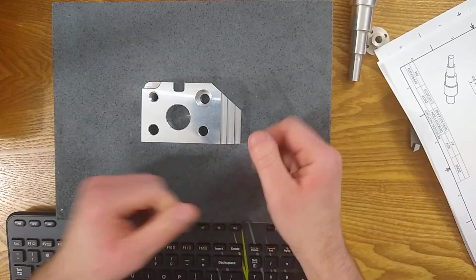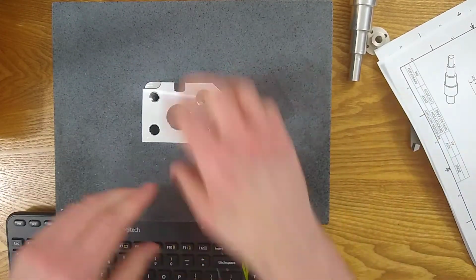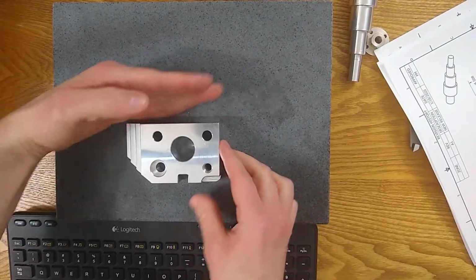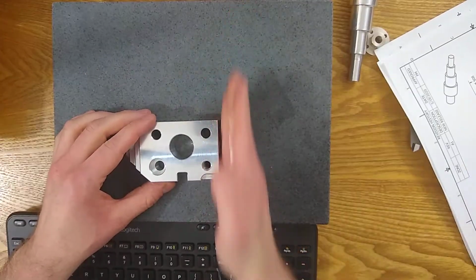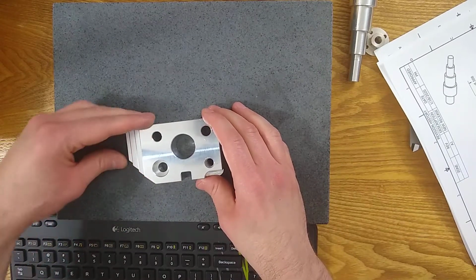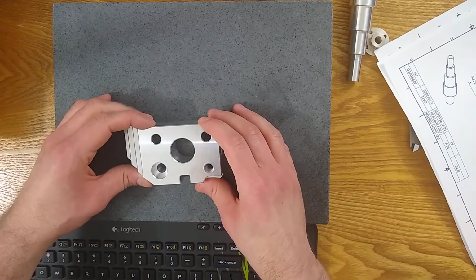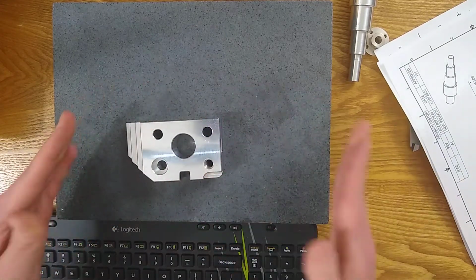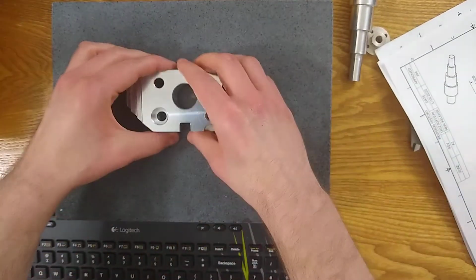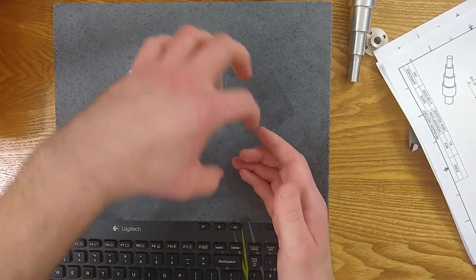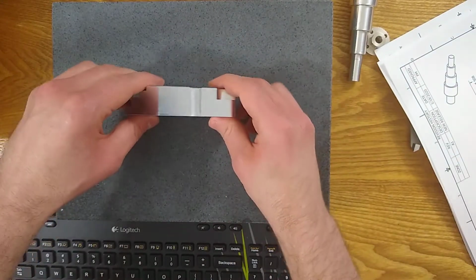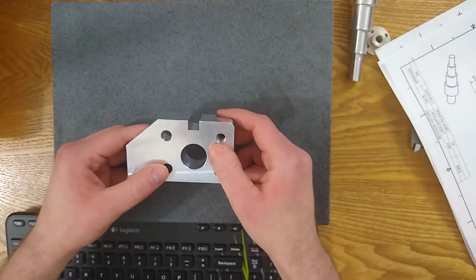And I don't have a machinist square here, but when you need to pick perpendicularity, you also grab a machinist square. You'll rest it along one edge, and whatever lines up on the other edge becomes your other datum. So when I do talk about GD&T, I'll be talking about that. But for this video, if you don't have datums, you pick the high points by using a surface plate or a square or an angle block. And in that way, if they're not defined, that's how you're going to have to define them.